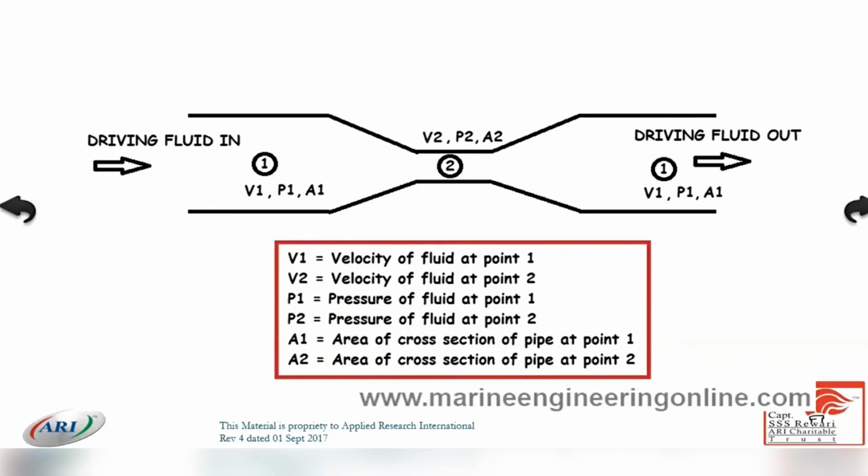They have made a well also inside the cargo tank, on the after side of the tank, where all the oil is flowing and getting accumulated, and the bell mouths are inside the well. So the stripping system has become very effective by this change in the construction of the tank. All longitudinals, all the transverses are on the ballast side of the bulkhead, not on the cargo side. The cargo tank looks like your room, plain walls, plain bulkheads, plain at the bottom, maybe some stiffening on the deckhead, on the tank top. But all the other bulkheads and the bottom are flat, like your room.